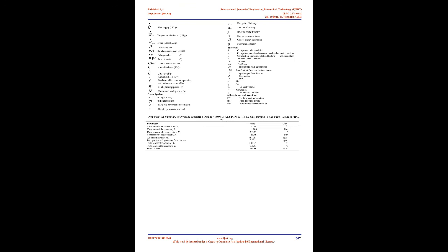Increased turbine inlet temperature improves turbine exergetic efficiency and net power output while lowering combustion chamber exergy destruction. However, lowering any of the turbine inlet temperature, P3/P4 value, or turbine isentropic efficiency is recommended to lower the capital investment, operation, and maintenance cost of the gas turbine. By installing a preheater after the compression process, the exergy destruction within the combustion chamber can be reduced as well. This will increase the exergetic efficiency of the combustion chamber and reduce irreversibilities.